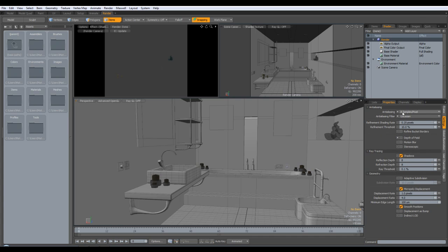Settings here. Now these do anti-alias, and we're going to come down from Gaussian and go up to box, which is the tidiest one. Samples is on 8. I'm just going to bring them down to say 32. But on the final renders, I'll probably go right up to 256 or higher. That's not going to add much time to the actual rendering, so I'm just going to bump that. I'm going to leave everything else as standard for now.